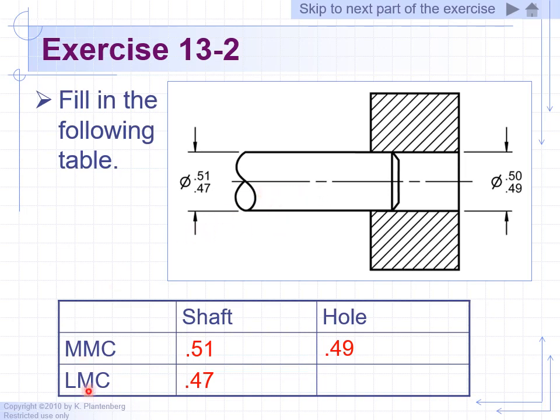It'll have the least material condition. It's when it's also at its lightest. And obviously for the block, we'll have less material when we drill the largest diameter hole allowed. So the larger the hole, the more material you're removing, and you're left with less material in the block. Okay, so the LMC, least material condition for the block, is when you drill at the maximum allowed diameter.